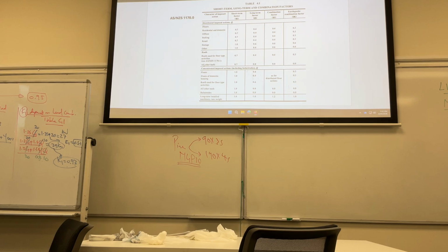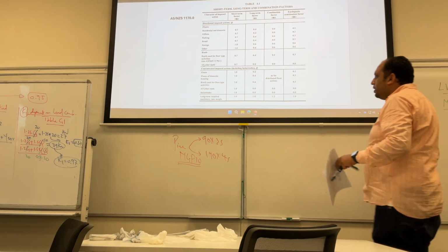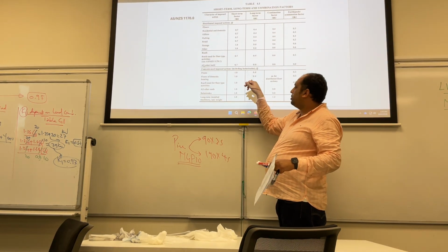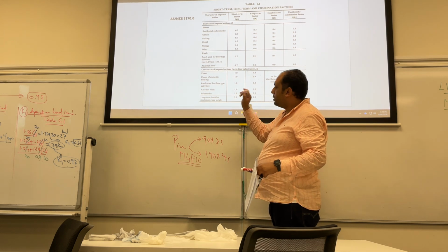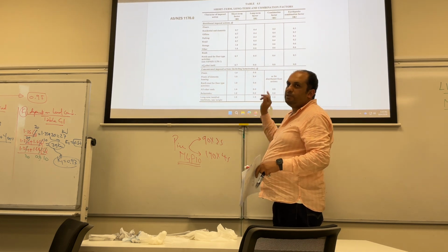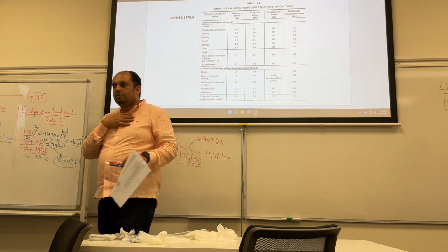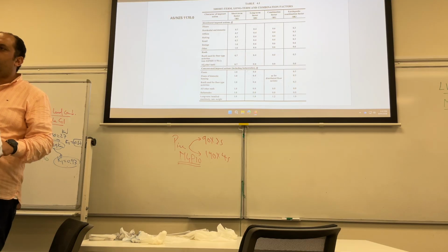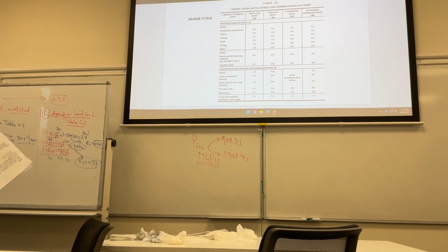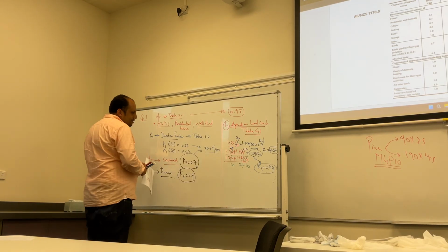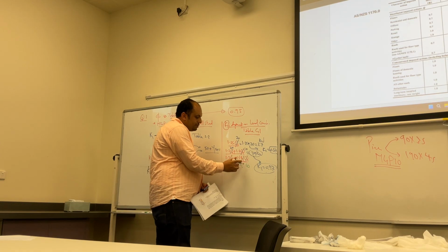It is not clear, but we can use it as 0 or what. It's up to you, depends on the specific case. In this case, if we consider it as roof used as floor, how much is it? 0.6. If it is all other roofs, like a normal roof with nothing above, how much is it? Zero. Do you know what is meant by roof used as floor? They use the roof to put something above it, for any activity. So if it is roof used as floor, this is 0.6.